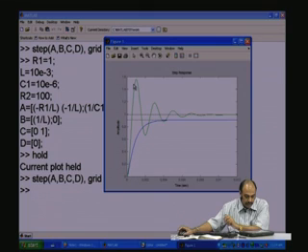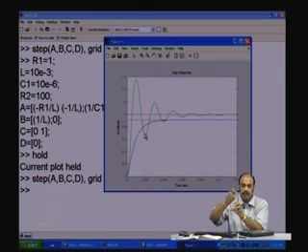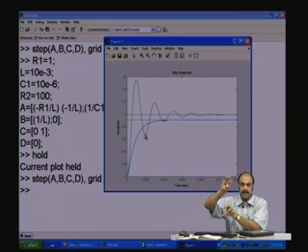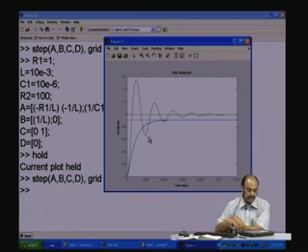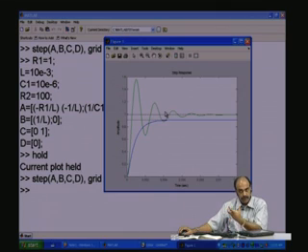And here, because you are getting overshoots, you will see that the 2 poles start moving towards the imaginary axis and they become complex. One is in the positive upper portion, and one is in the lower portion, which is the negative. One indicating capacitive effect, one indicating the inductive effect. So, if you have any such oscillation, you should have 2 effects, which is the capacitive and the inductive effect, which is what we are having in the RLC circuit. This is the interesting point that you will see once you keep varying the parameters.